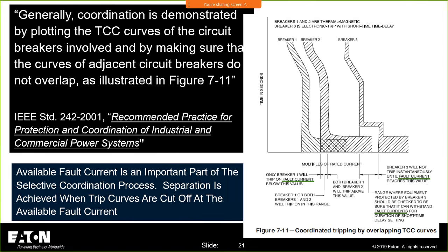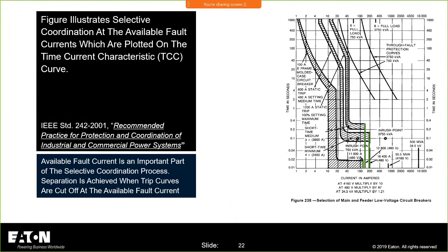When I used to do this, I got a passion for it because I worked for Gilbert Commonwealth and did a lot of these studies. I would sometimes put 3 overcurrent devices on the curve, or 2, depending upon the system. But you're basically comparing these overcurrent devices with either the equipment that you're trying to protect or other overcurrent protective devices that are upstream or downstream.